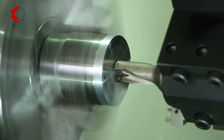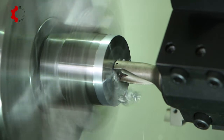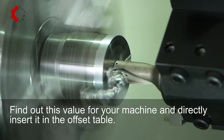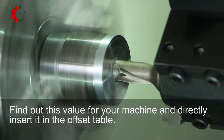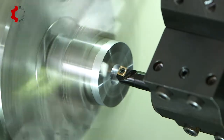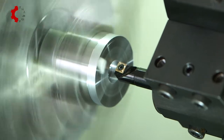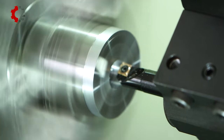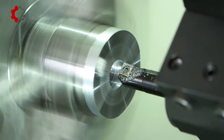Taking X offset of drills. While drilling, the drill has to align with the spindle axis. The X offset value of drills is a distance between two fixed points, so it is a fixed value for a machine. Taking X offsets of boring bars. The procedure is similar to an external tool with the difference that now cuts are taken along X plus and relieving is done along X minus direction.